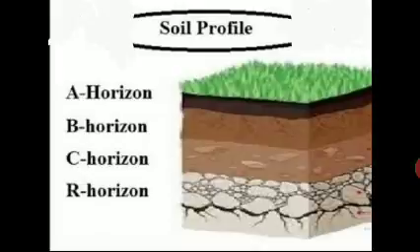The next physical property is texture. The size of particles comprising the soil determines its texture. The texture of a soil is perhaps its most nearly permanent characteristic, although soil structure can be quickly modified by management. The texture commonly refers to the fineness or coarseness of soil as a whole, as to the proportion of the particle groups of different sizes. It is controlled by climate and mineralogical composition of the parent rock.